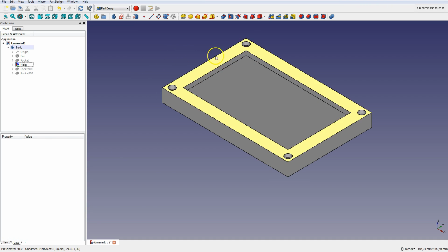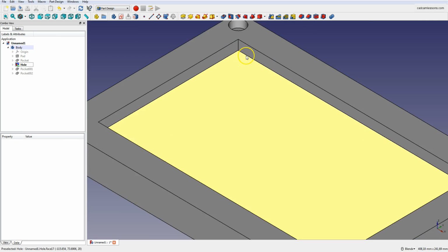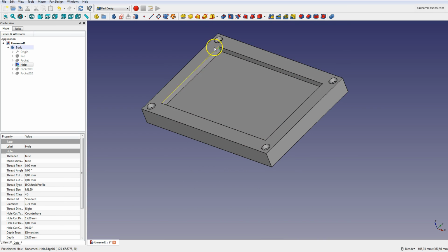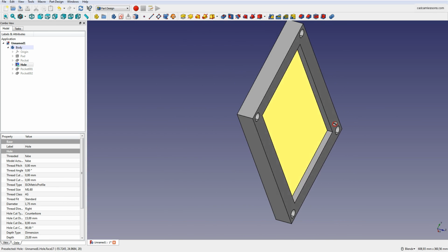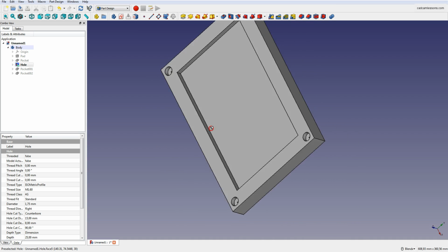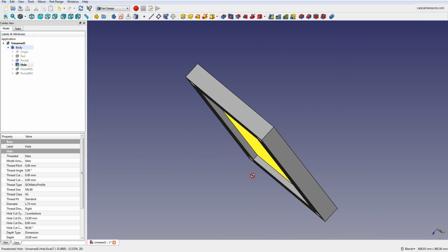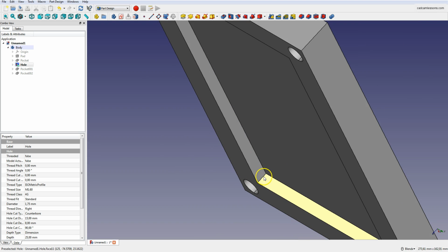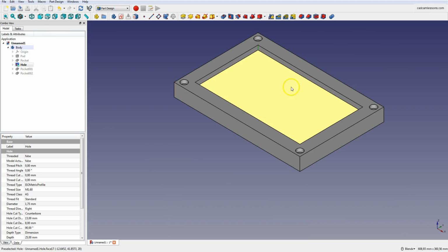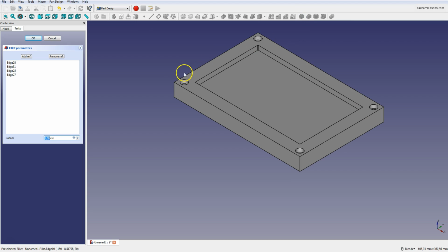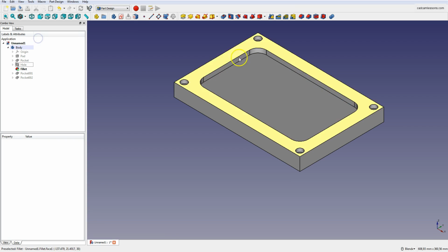First we add fillets for these edges. We have to select for these edges with Ctrl key pressed. Okay. Okay, and now let's select make a fillet on an edge face or body. Okay, and here type 20 mm and click OK.